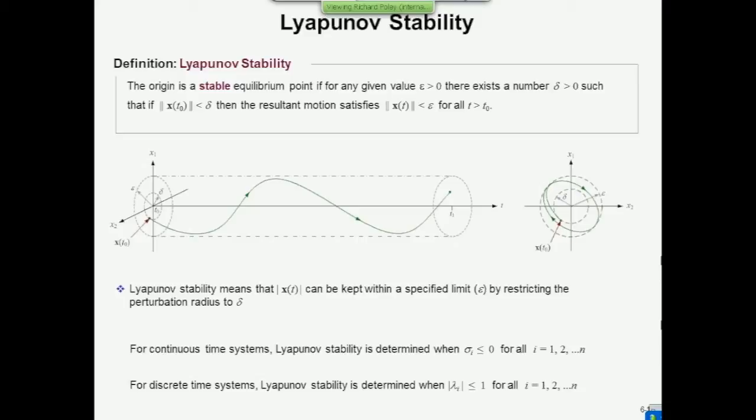It's called Lyapunov. Sometimes you see systems which have Lyapunov stability referred to as stable in the sense of Lyapunov. It's not something we need to worry about too much, but the terminology comes up from time to time, particularly with relevance to nonlinear systems. But a system which does this, and in this case it's second order, so its phase portrait would fall into the category of center, it possesses Lyapunov stability.